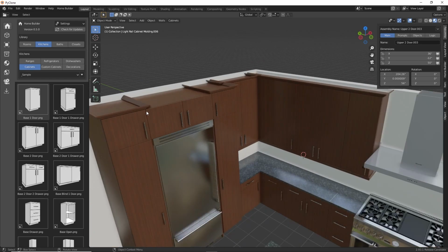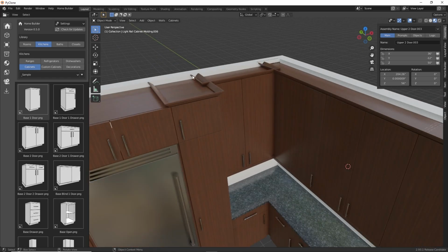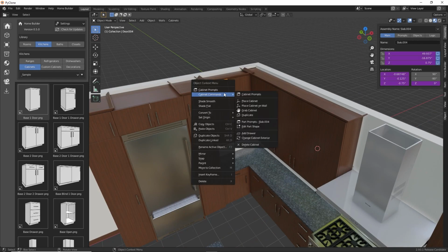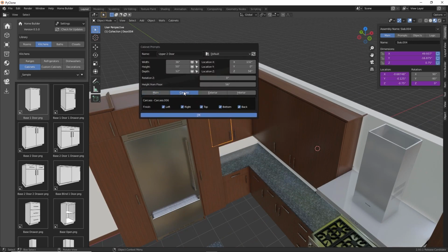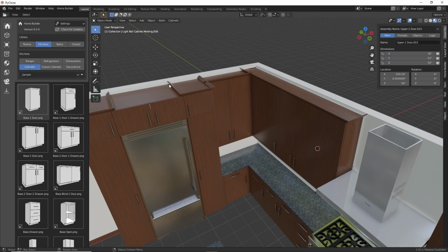And so here we can see that I'm not applying molding to the appliance cabinets yet, and there's some issues that will add returns when there doesn't need to be. And right now this is all figured out based on the finished end condition. And so if I would have selected this cabinet and went to the carcass and set the finished option and turned off left and right, and then here we can just rerun that same command, add molding to room, click OK. There it will not make that return,